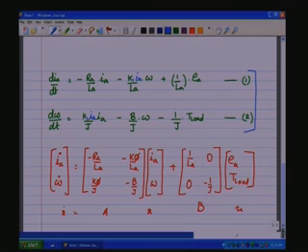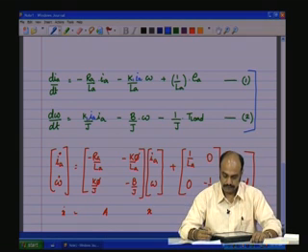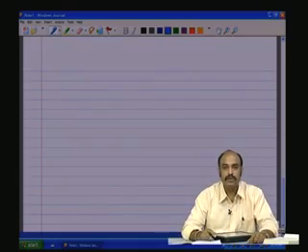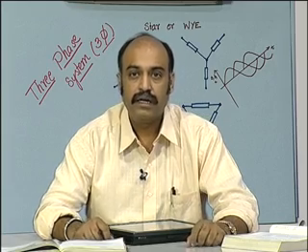motor system. So, the phi should appropriately be modified, whether it is a constant or whether it is now a function of I_A or any other variables, that should automatically be put in there, and that will give you the complete dynamic model of the DC motor in the state space form or differential equation form. Okay. So, with that we conclude our discussion on DC motors.